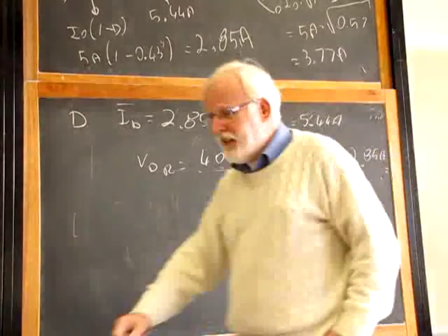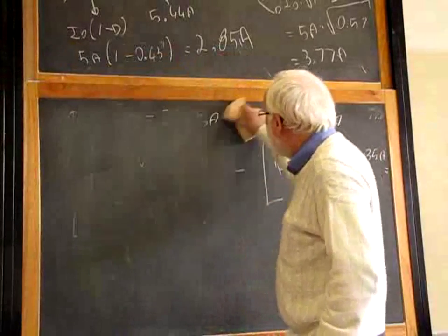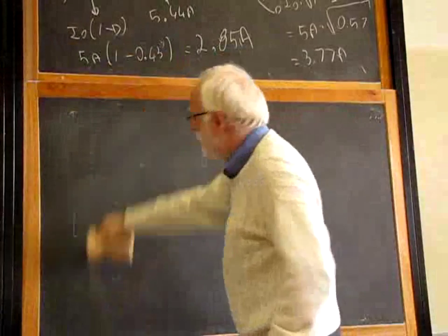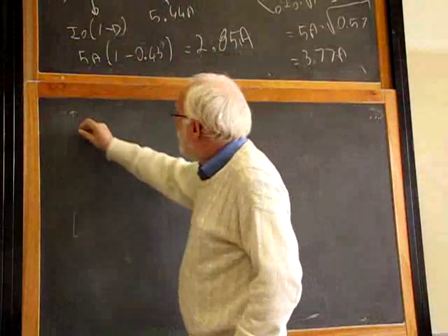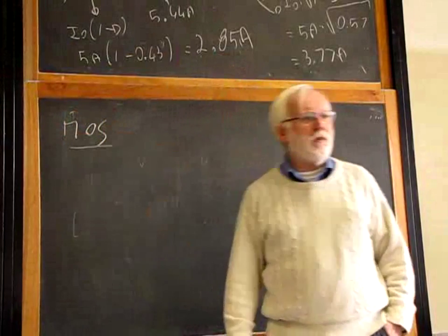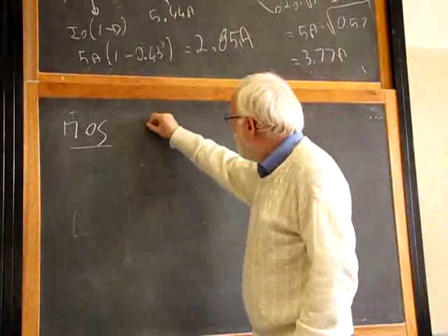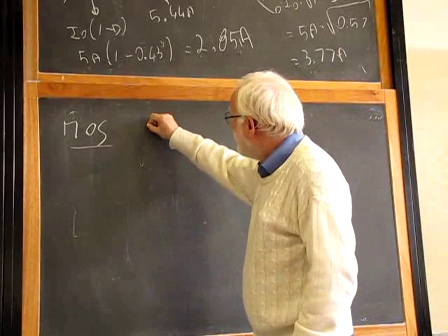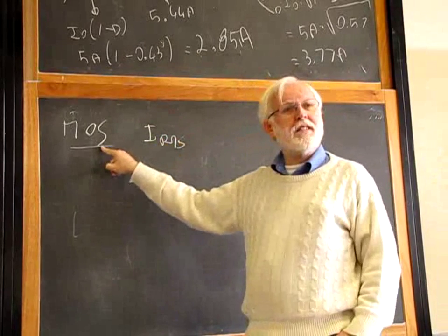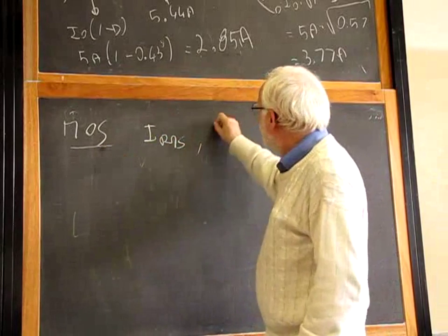Diodes. If it is silicon carbide or Schottky, it's basically fast. If it is standard, you have to specify that it must be a high speed diode, faster. Switch, MOS. Most of the time we use MOS transistors in this class. So for the MOS transistor we need the IRMS, because a MOS transistor when it's on is basically a resistance. We need I peak.